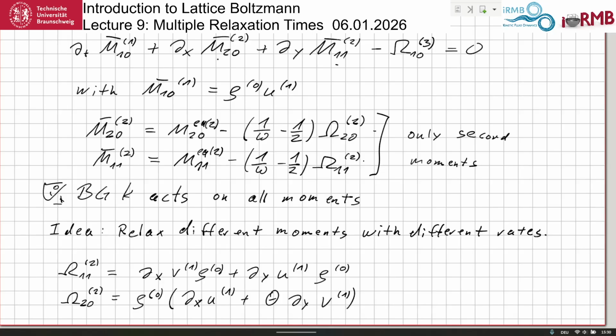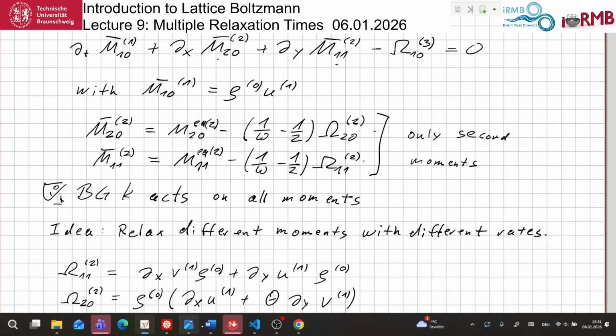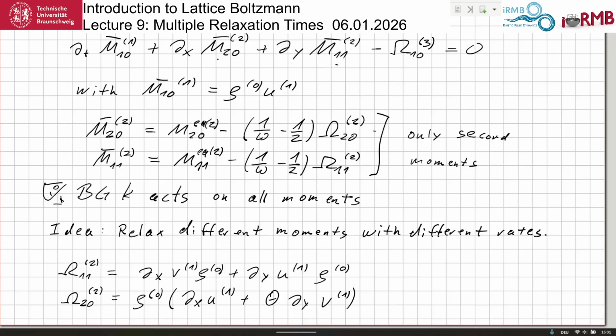So now what we observe here is that we have u x velocity derivative in x direction plus the y velocity derivative in y direction, which is the divergence which we have identified to be, to leading order, 0. The divergence of the first order of velocity is 0. Yeah, however, this thing here is not 0 because theta is not 1. So this doesn't help us.